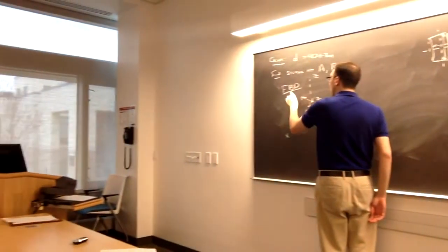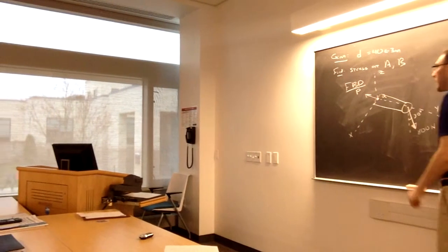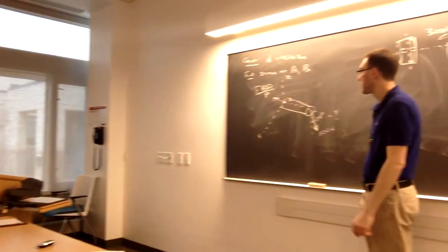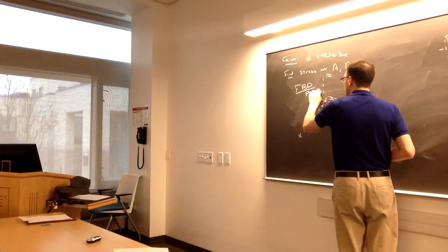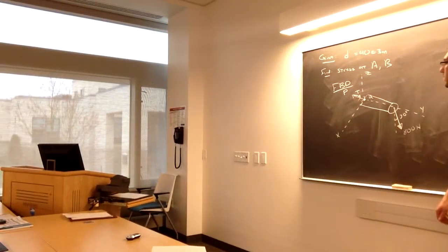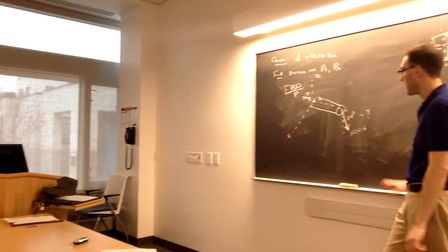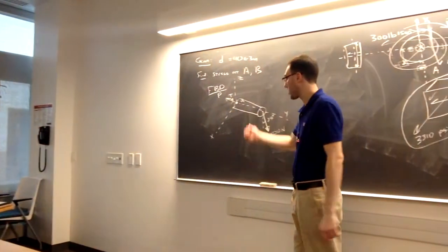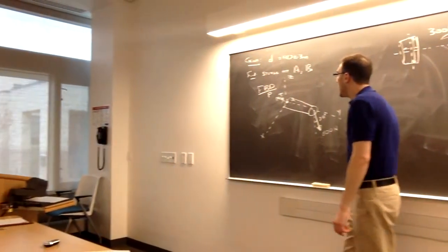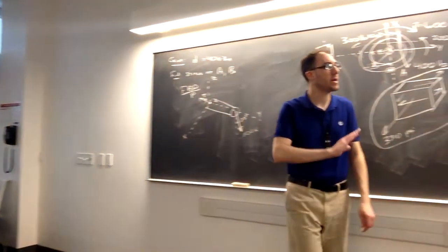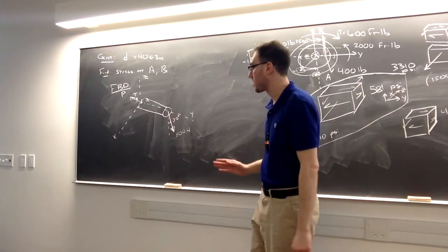So first is the value P coming out from that cut surface. And then immediately I know that my assumption is that T is positive around that axis. So it's going to be around the negative y-axis according to my global coordinate system. And then my shear force is going to be along that cut surface.